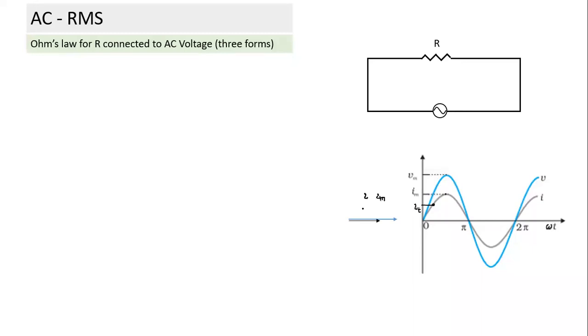And the third is IRMS. We also call it RMS current. Sometimes we also use the word apparent current. Apparent current means though the current is varying, it will appear to be equivalent to an RMS current having a constant value. And this RMS current, I can represent as IRMS, or many times we also represent it as capital I. So capital I represents the RMS value of current.